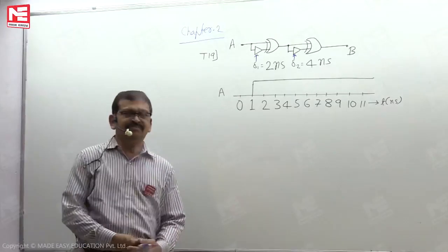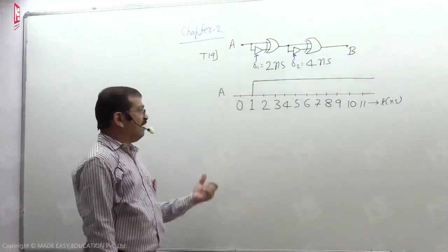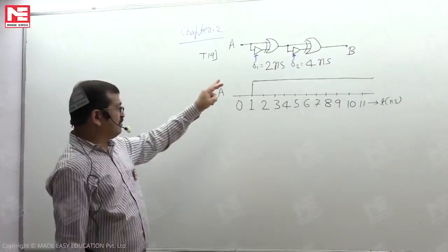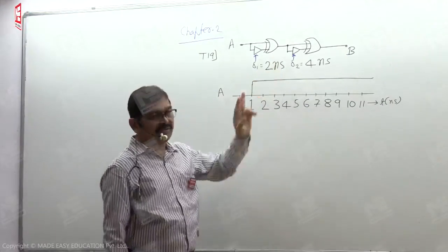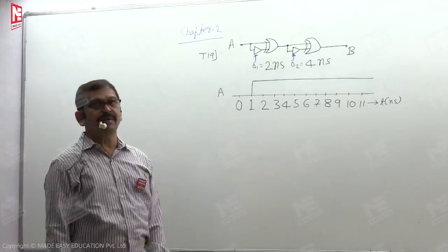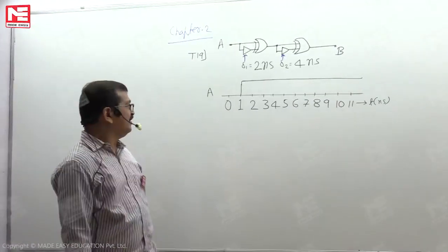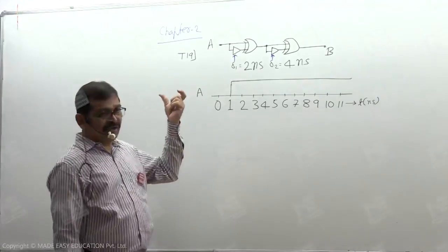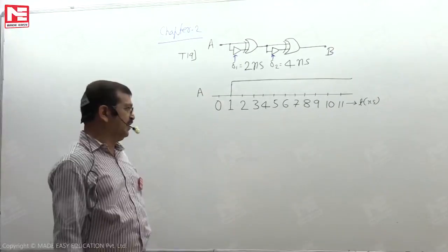So basically, in this circuit we have two exclusive OR gates and two non-inverting buffers. One of the non-inverting buffers, delta 1, has a propagation delay of 2 nanoseconds. The other non-inverting buffer, delta 2, has a propagation delay of 4 nanoseconds. And based on the question description, no other devices, particularly the XOR gates, or connecting wires have any delay.